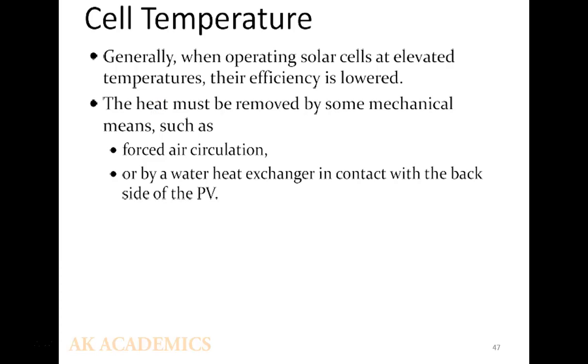And when we are able to do this, the temperature reduces and then the efficiency of the PV module can be restored. Then we begin to get the best output from our PV plant. This simply means that at every point in time, we have to find a way to ensure that the cell temperature is not too high. When it is elevated, the efficiency of the system decreases.